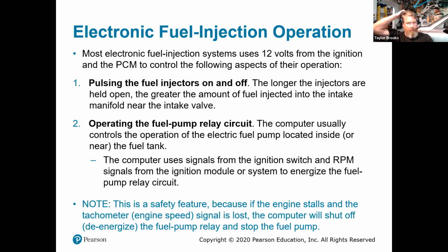The first and foremost is we have to have some sort of control. Unlike a carbureted engine, which is going to be using mechanical means to atomize the fuel and air mixture, we are going to be utilizing the computer via a series of input sensors to be able to spray the fuel injectors at the correct time. Now, there are going to be some programming differences between the different ways that we can fire these injectors, and we'll talk about that in the later slides.